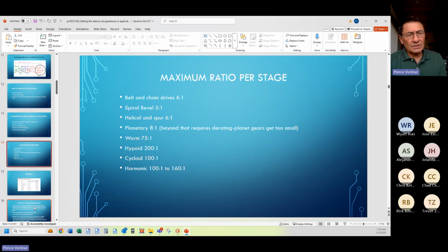We're not going to focus on those too much today, but later on in this presentation, for those of you that missed the previous class or want to review it, there are links to videos that show you what cycloidal and harmonic gearing are. And yes, they are very compact, have very high ratios. They also happen to have zero backlash. These are very special gearboxes. They're also very expensive, but when you need them, you need them.